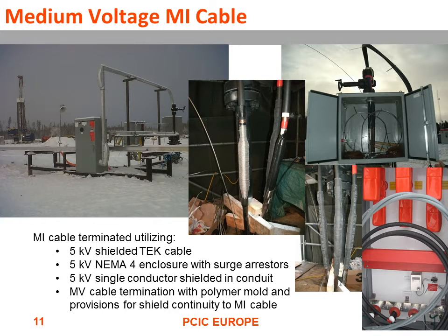And here are some of the electrical components that we used in the application. The middle slide shows the end terminations where we go from the MI cable into the medium voltage tech cable. There was a special connector that was designed for this by both 3M and Tyco Electronics, so there's sort of 2 vendors for this, and it has stress grading in it and all the things you need to go from an MI cable system into the tech cable system. You can see the partial assemblies in the center picture.